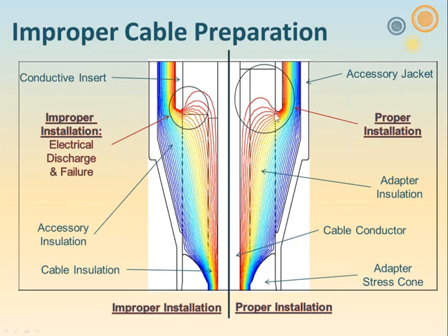Let's look at it a little deeper. This area right in here, we said we have 40 volts per mil along the interface. Perpendicular stress may be 50 volts per mil. Now, 50 volts per mil in EPDM is well within the operating voltage of that material, certainly within the operating voltage of cable insulation. On this side, you can see that that stress line is bending a little bit more. When you do the analysis, it may end up that we've increased the stress. Instead of 50 volts per mil, now we've got 55 volts per mil. Again, you might be saying, so what's the big deal?